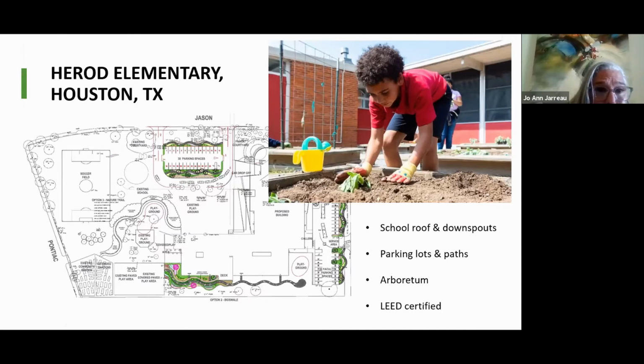A lot of times, if there's not a type of border there, it will wash the actual planting bed out into that bioswale, and you have to continuously redefine that bioswale. So borders are really important when you're talking about bioswales and directing water, but you have to make sure that you put them in the right place.